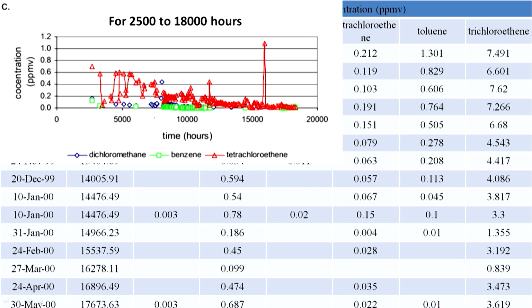That means that they have not obviously pumped the gas out continuously, right. They let the system rebound, right. As in, there is this mass of contaminant in the gaseous phase, I remove this, and then if I keep pumping it, what is going to happen? I am only going to keep pumping out relatively less contaminated air. So, the efficiency of my system is relatively less. So, what would I do?